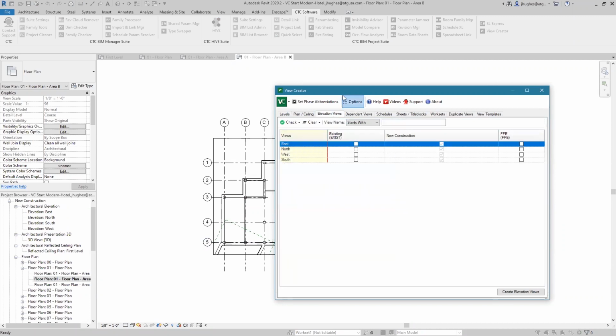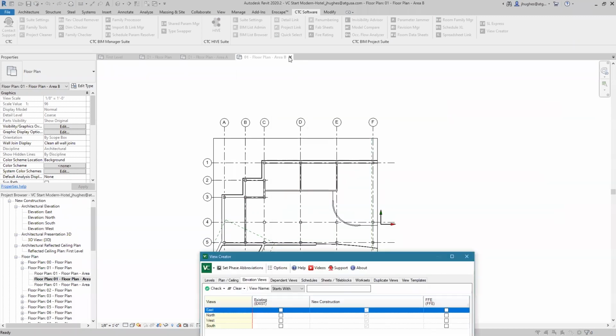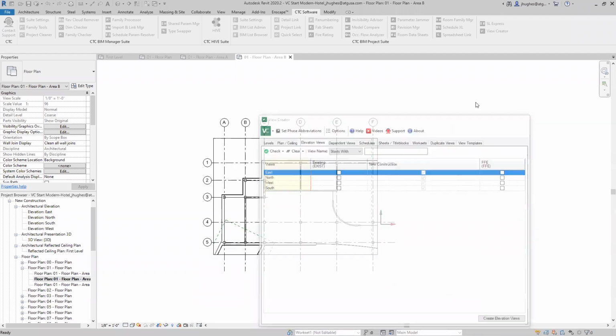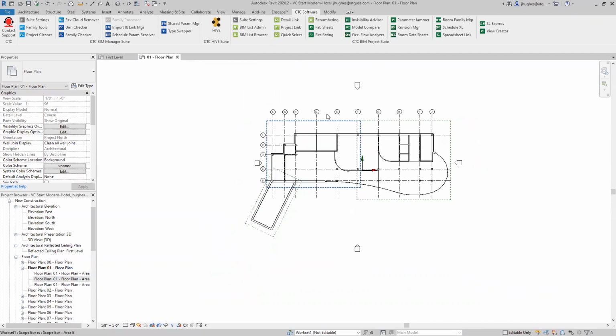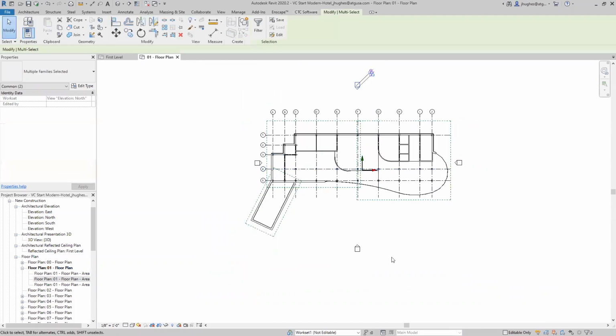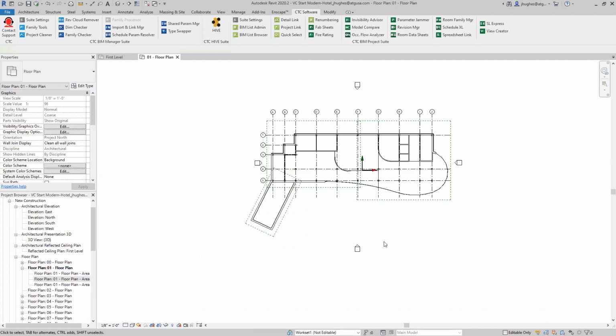Now we have a few elevation views on the outside of the building. I picked the wrong view to be able to show that. Let me go back to a main. Right, so we've got some elevation views around the outside of the building. We also have multiple phasing. We have 3 phases: existing, new construction, and then a later FFE. Now, we do need to have elevation markers at each of those phases except for FFE. We don't need any exterior work for that, but we do need existing and new construction building elevations created. And you can even use the tool to very quickly do that.